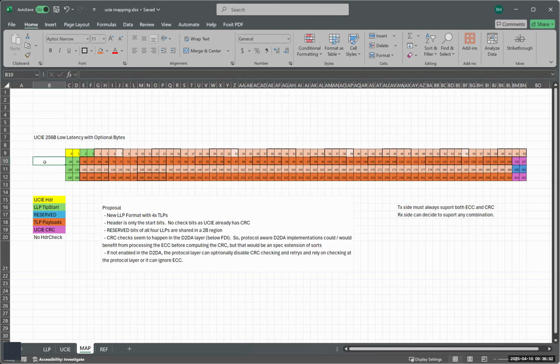Well, I take that back a little bit, because you can kind of infer, because this is the preceding one, and as this one's aligned, then you can infer. Well, there's a limited amount you can infer without the header. You can infer what would be the... what's the word? One protected, one large code word. So for the first handful of bytes, you can infer where the ECC is based on the previous header, but you're very limited.